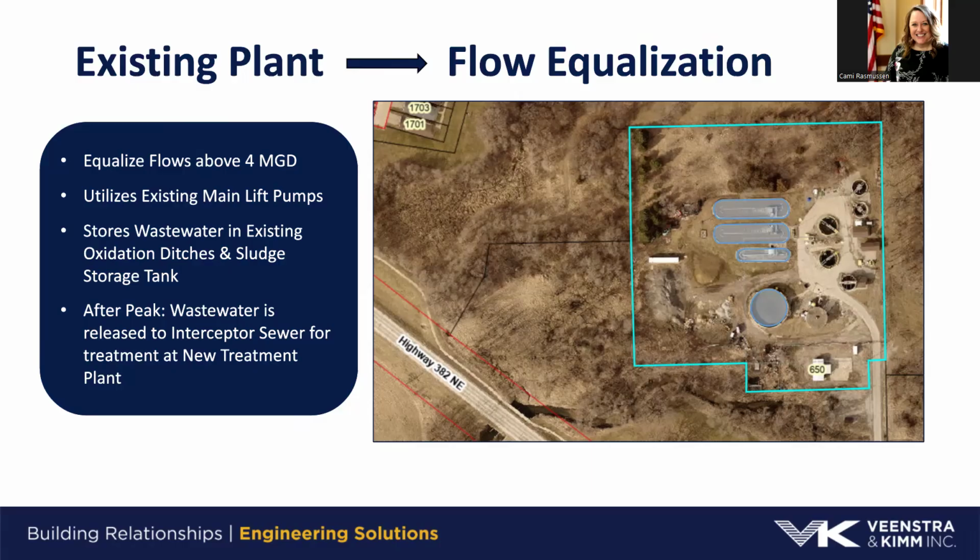If we were looking at a situation, as Emily mentioned, where we were putting something in there that had some issues because we didn't want to run it through the plant, that may have some odor associated with it. But once again, we're doing it because there's contaminants in there that we don't want to run through the plant, and we have to be able to address that, whether that's coming in and pumping it and hauling it up to a facility that can handle that because they have enough volume that it's dilute enough, or whether we could bleed it back slowly and not affect our plant operation. We just have to make sure that we don't have what's called pass-through and interference. If it goes through our plant and doesn't get treated and goes out to the lake, that's a problem. We can get fined for it.